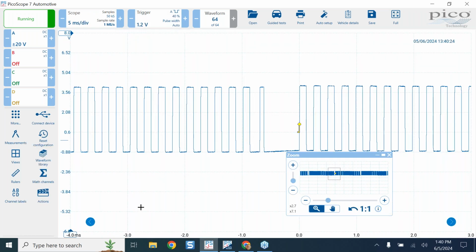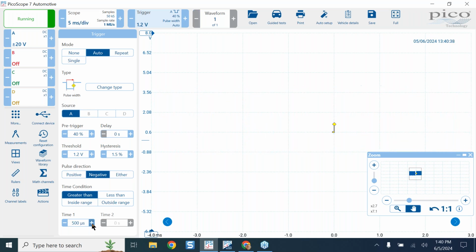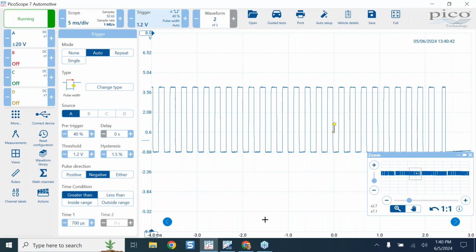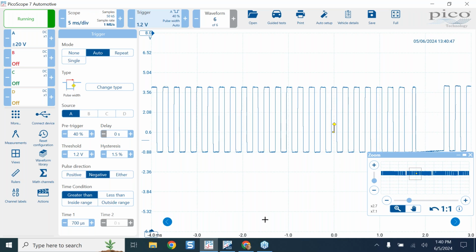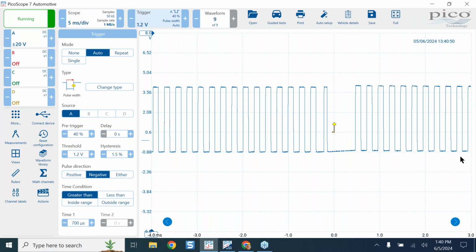And I always, as I said before, like to break my triggers. So if it's triggered properly, I want to make sure I just didn't get lucky. And so I'll go back in here to my time, and I'll raise this so I know it's going to be above the window that I measured, and you'll quickly notice that now we're all over the place again.